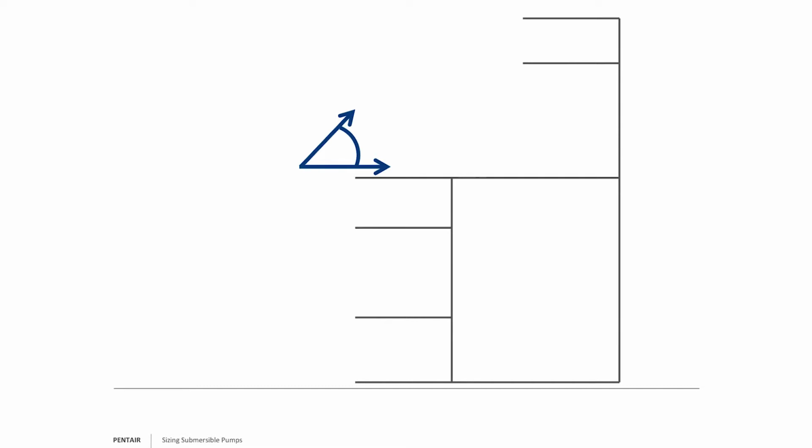I want you to make sure you understand, and I really drove this point home with the earlier webinar that was on submersibles, that when you tell me total, that means you took into account the total dynamic head, including friction loss, all the way down to where the pump was set. If that pump was set down 1,000 feet, I assume, and I hate to do that, but when I hear total dynamic head, that you did the friction loss for that 1,000 feet of drop pipe.